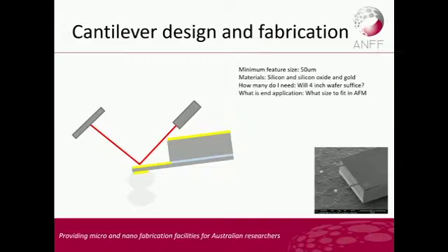So anyway, we built it on a 4-inch wafer. That gave them, I think, a couple of hundred devices from every single wafer. And then we have to think, well, what's it going to fit in? It's not going to be packaged, but it needs to fit into an AFM. So we go and measure an existing AFM cantilever and see what size we need in order to fit onto the AFM.